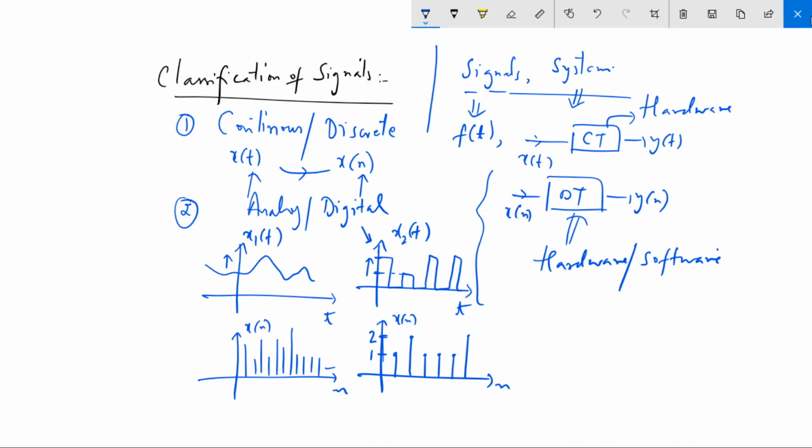So this is digital signal, continuous time. This is continuous time analog signal. This is discrete time analog signal, because see, in this case your time is discrete in nature, but the amplitude is not discretized. In fact, it is again continuous. Amplitude is again continuous and it can take any value. So this is again analog signal. This is a digital signal and also a discrete time signal.